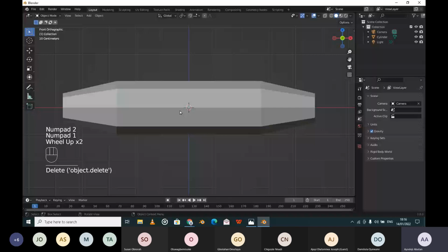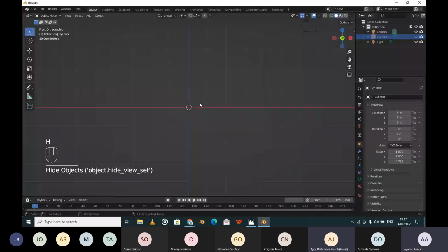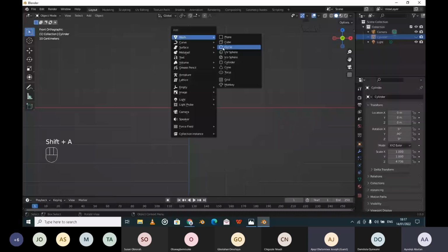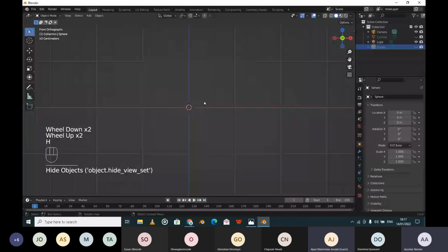So to add an image in Blender, sorry, let's hide this. I'm using H to hide objects, by the way. Anytime an object disappears off screen, it's H I'm pressing. I can't be mentioning everything I'm doing all the time. To hide an object, you're not deleting it, you're just hiding it off screen. Click on the object and press H. That hides the object. You can see it down here on our screen cascades. I just realized I didn't mention it.